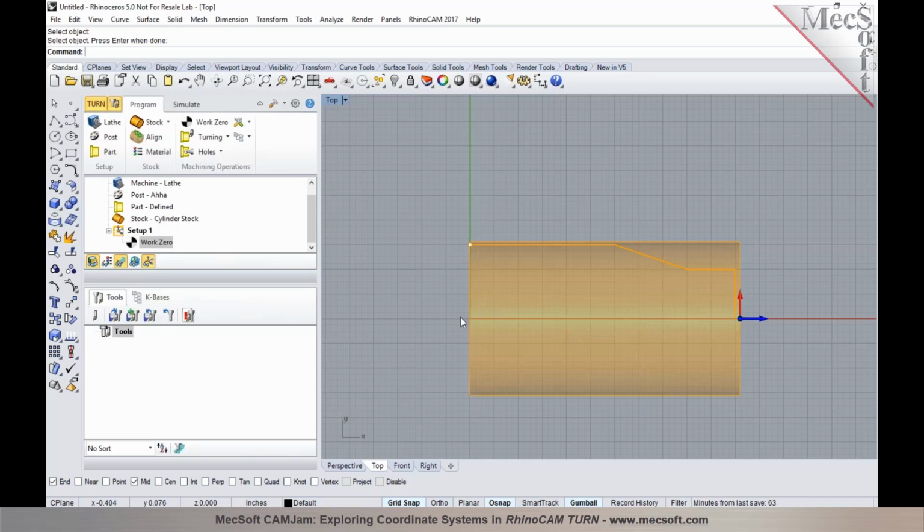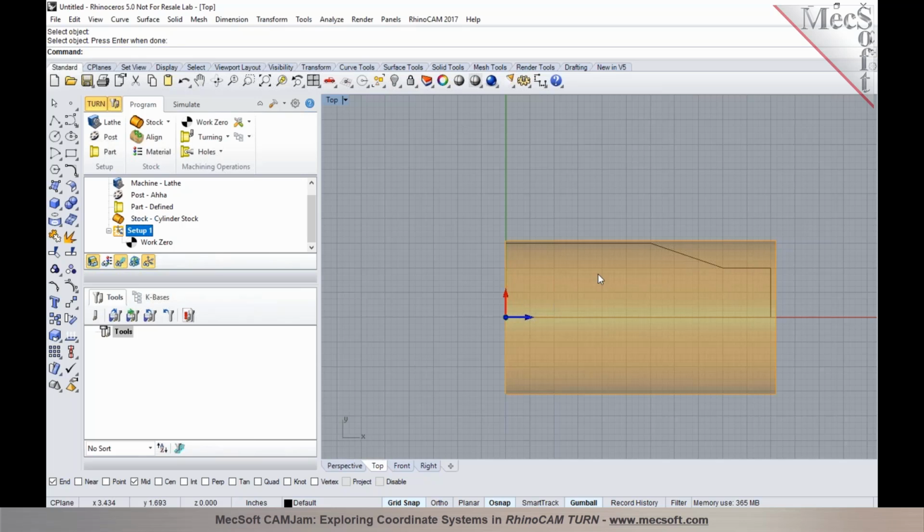But when you design the part and orient it, you need to make sure it's established at the backmost face in here. Now, this would be similar also in SolidWorks. We'll talk about how, when we import a file and it's in a different orientation, we can easily orient the coordinate system for turning. So it's important to make sure that the back face of the part is at the origin.